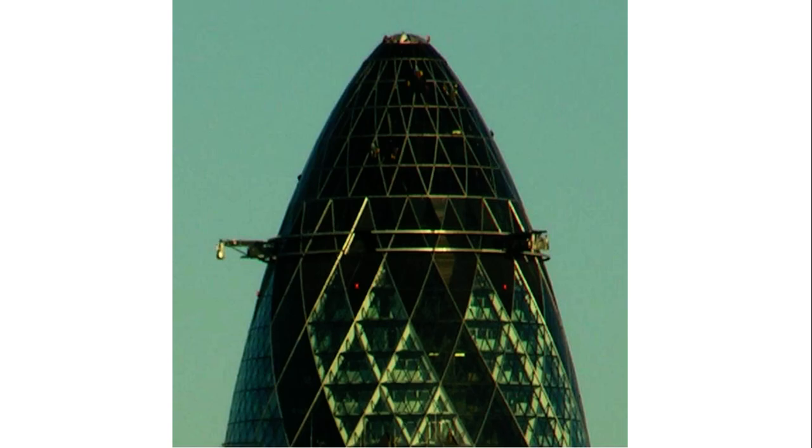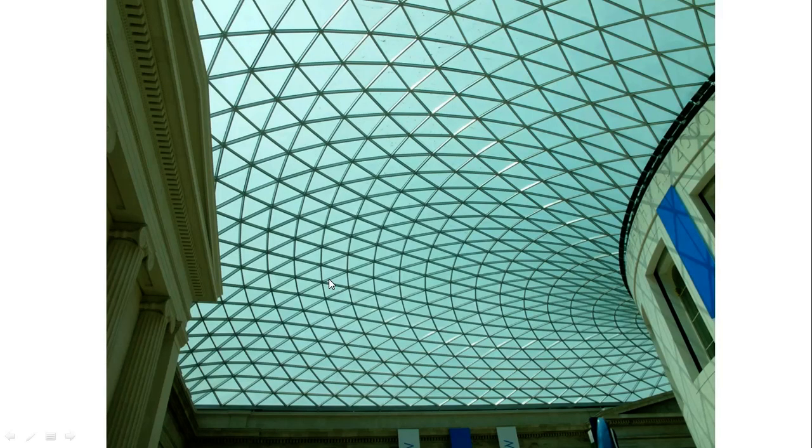And as I think I mentioned earlier, it's a slightly different kind of tower, because this is a tower that, instead of relying on a big, huge concrete central core taking most of the load to ground and giving static equilibrium to the structure, uses an exoskeleton. It's the lamella structure on the outside. This is all steel. You can just about see it here. These are big steel sections that the floors are hanging off.